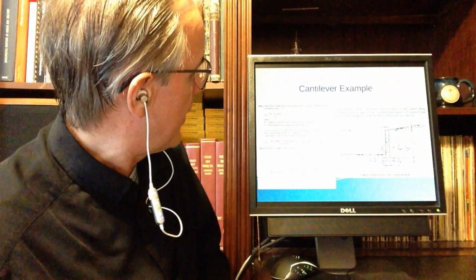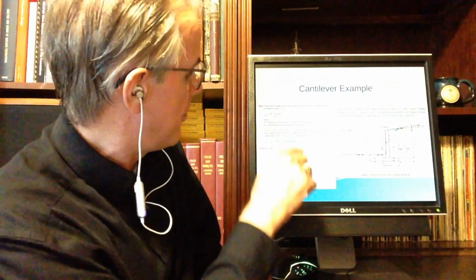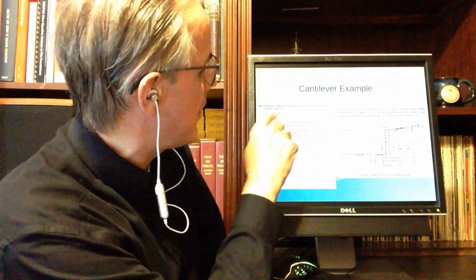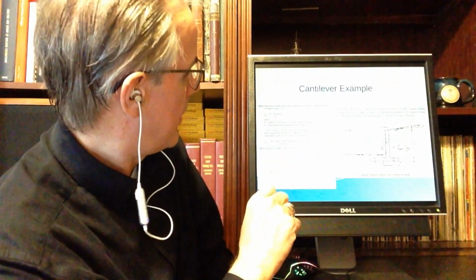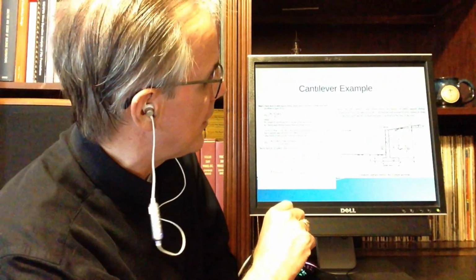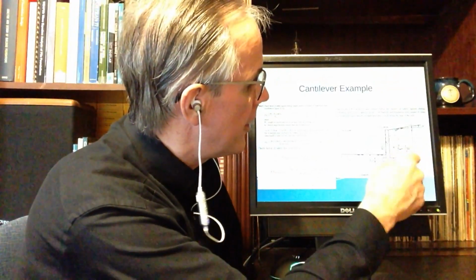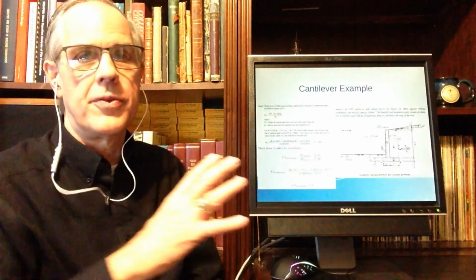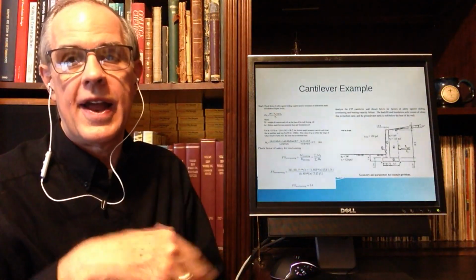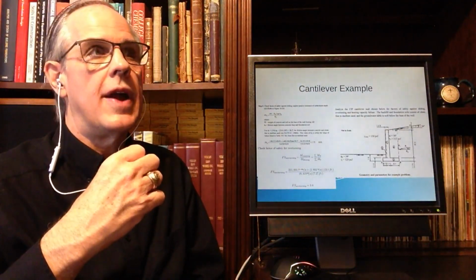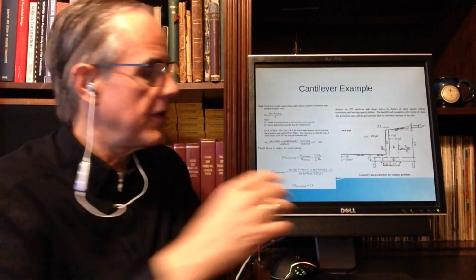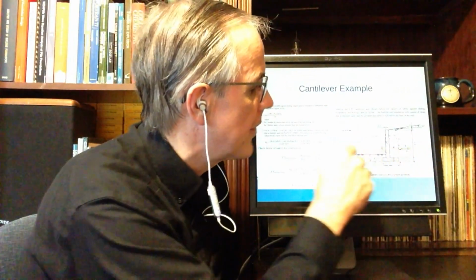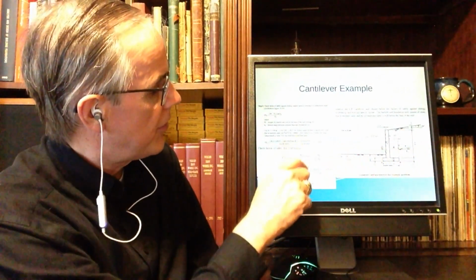But that gives you the depth, and you plug and chug, and then pH is the horizontal force. Basically, it's the same old thing we do with retaining walls all the time. We have sliding forces and resisting forces. The resisting force is basically the frictional force along the bottom, and the driving force is this pH right here. The ratio of those two is your factor of safety.